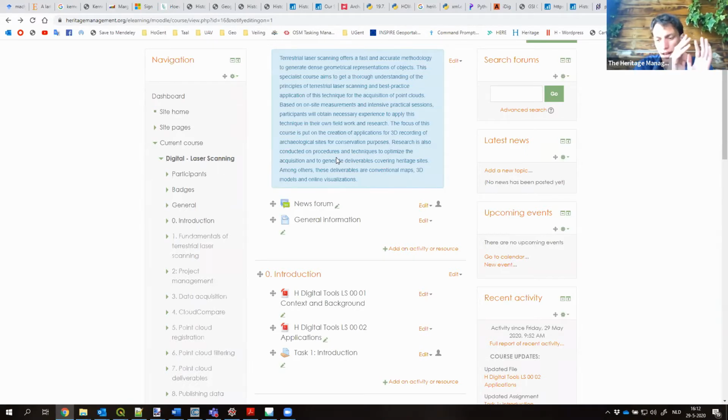The photos were converted to a 3D model, and from the moment that you have your dense point clouds, you will make an LAS file using the export functionality in Metashape, and then you can pretend these data to be from a laser scanner, and all the exercises can be done using these data.